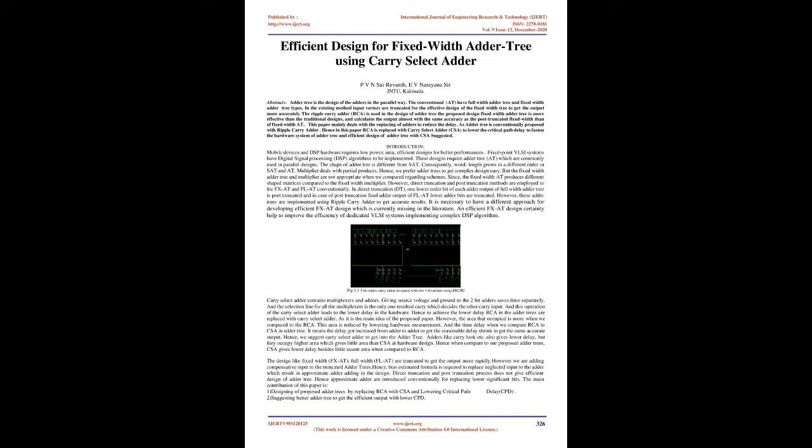Multiplier deals with partial products. Hence, we prefer adder trees to make complex designs easy. But the fixed-width adder tree and multiplier are not appropriate when compared regarding schemes, since the fixed-width ED produces different shaped matrices compared to the fixed-width multiplier.